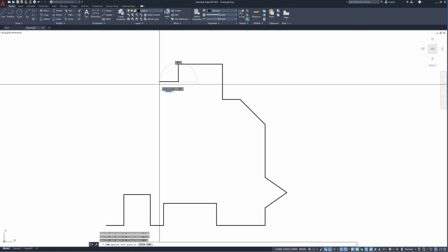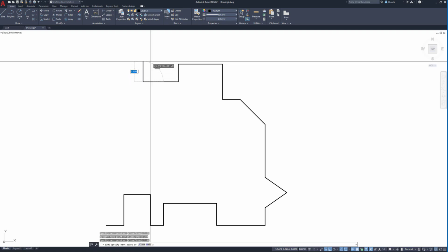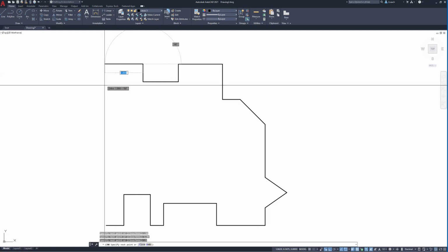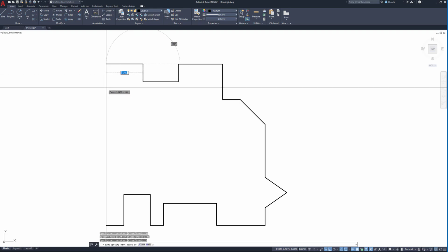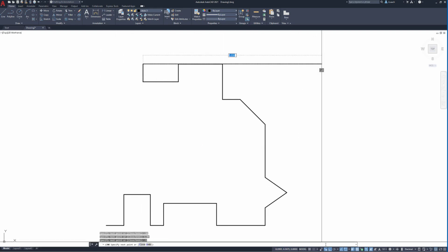Anyway, now where I was. Oh, yeah, to the left. To the left, 1.00. I'm going to go straight up, 0.5. All right, so here we have an angle. It's an angled line, but we're not given the degrees of that angle, but we are given the X and the Y value. So what I'm going to do is turn my ortho mode off. I don't really think I need to, but I'm going to turn it off.